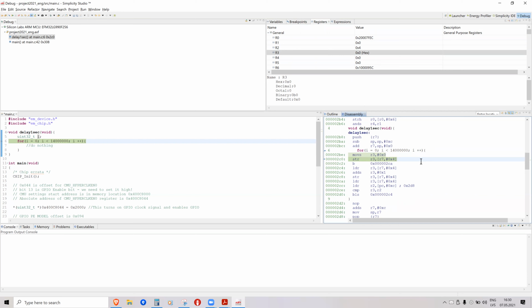Next, it is probably compared with some value, and basically move, store, load, add, these usually are fast instructions. So addition of registers is one clock cycle, but branches are slow. They are something like 3 cycles. Loading usually takes 2 cycles, but if it's copying from register to register, it's just 1. So we can approximately count how many lines is one loop. So I'll just count it.